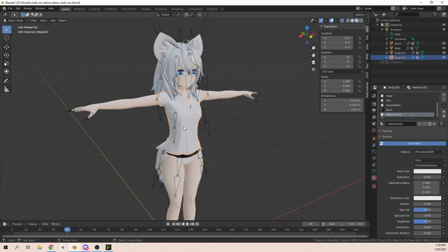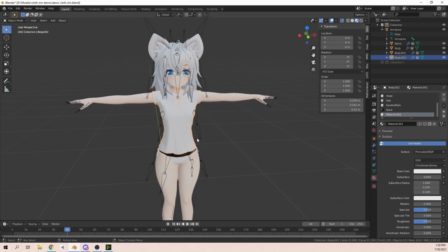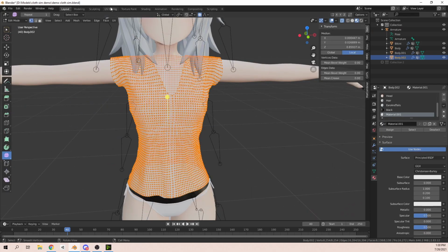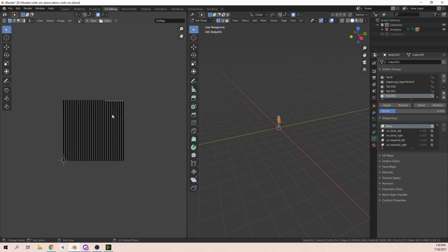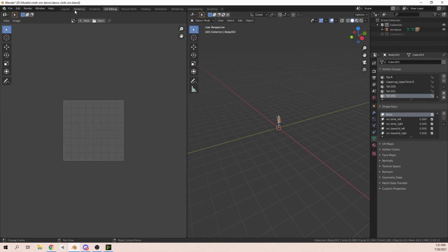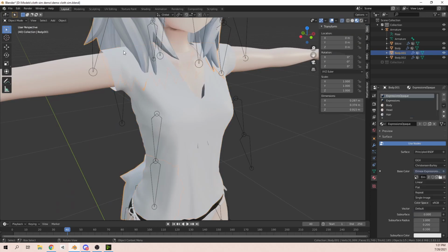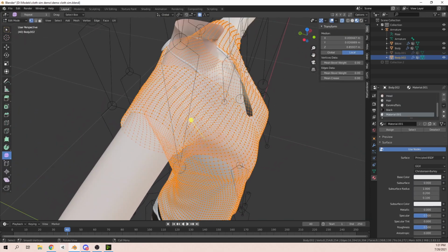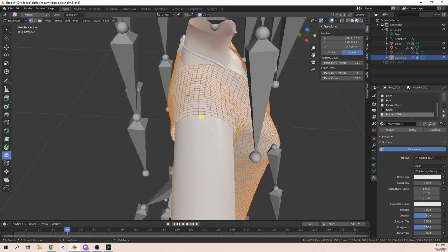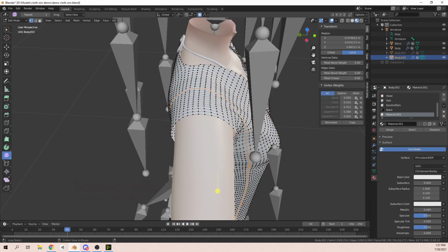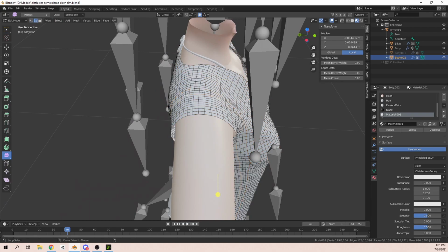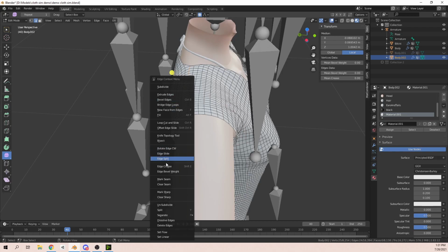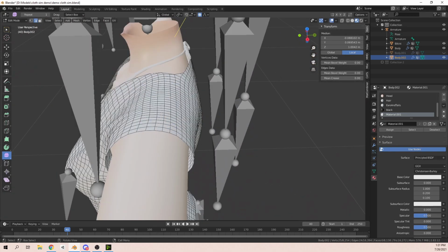The last thing I'm going to cover is getting you started with texturing it. Currently, I don't think there are any good UVs on it. So what I'm going to do is split it into two parts, and I'm also going to do an AO bake. I need to go into edge select mode and select this edge. I think this is a good edge to use. Mark it as a seam.